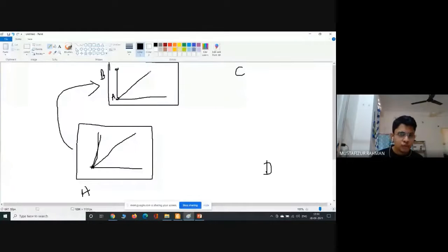Now from B, we will draw our lines. Okay. From B, we will draw our lines. We will join B to D. We'll join B to C. And we will be taking corresponding offsets, all the objects, whatever is there nearby, we will be measuring all those things.